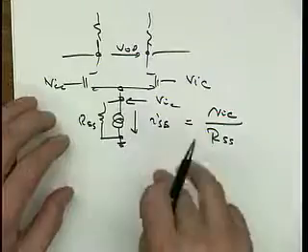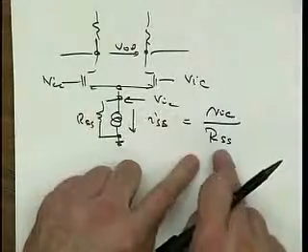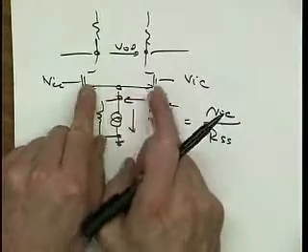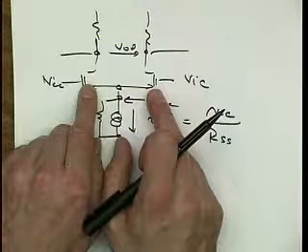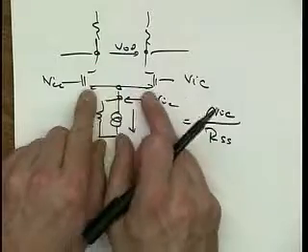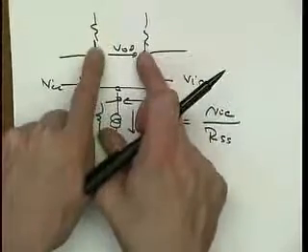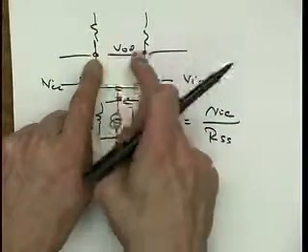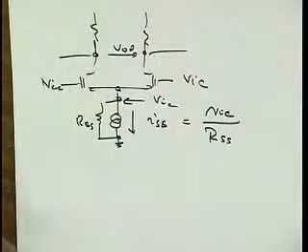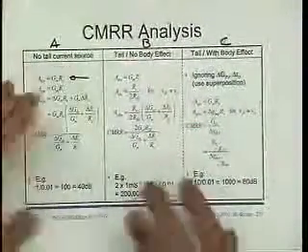Now I have the same argument again as before, that this much smaller current is going to be split according to the mismatch of GM and produces an output voltage. Or alternatively, the GMs are equal, so the current splits half and half, but because the resistors are not equal value, I still get a voltage difference developing between them. And once I have done that, the analysis is exactly the same as we've done before, and I've given the equations here. So I just plugged in some reasonable values for RSS.